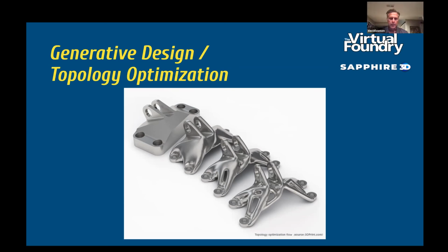And what I would add to that, and it's been my experience, is that a very large blocky part at the beginning will have distortions. You've got to get the gas out of that part, the plastic, during debinding. So you think about the thin wall by those holes on the perimeter versus the thick part internally, the heat dynamics are going to be very different.